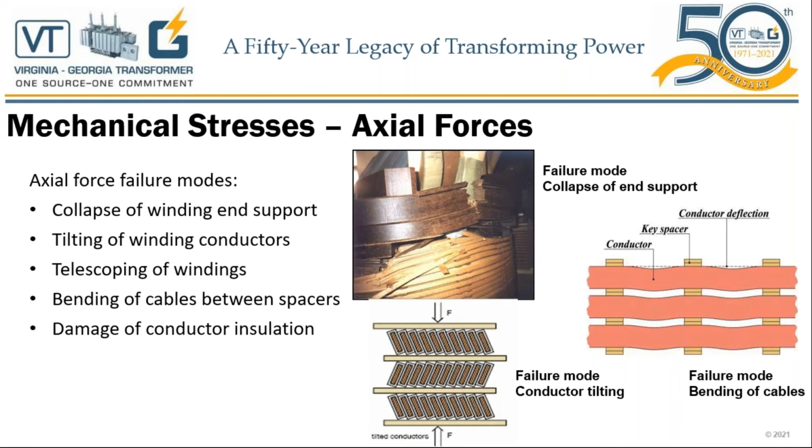The force is calculated mainly using the short circuit, the fault forces of the transformer. Even the thickness of that material, how many key spacers per column we're going to use, everything is defined using those short circuit forces and clamping forces and even the lifting forces. There are so many different aspects of calculating this tie plate and applying the jacking pressure on the windings. This ring has been broken, obviously, you can see in this failure. So this is actually a short circuit failure mode that has been seen in the field.